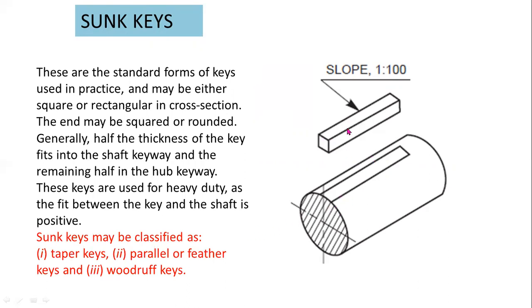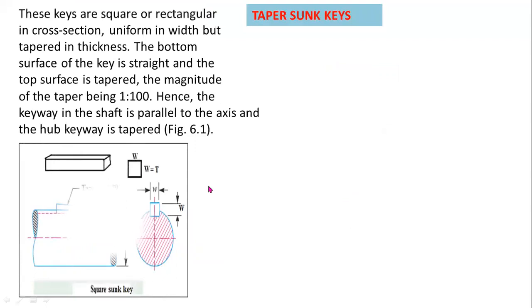These keys are used for heavy duty shafts as the fit between the key and the shaft is positive. Sunk keys may be classified as taper keys, parallel or feather keys, and Woodruff keys. Taper sunk keys.